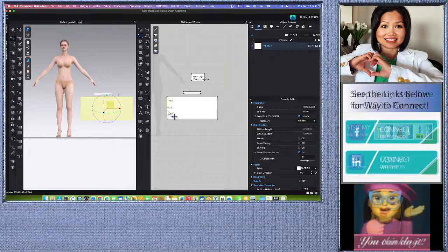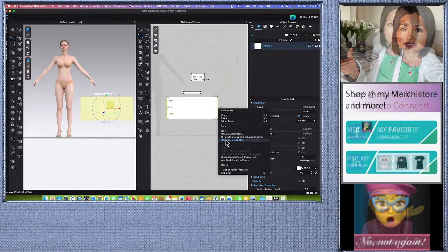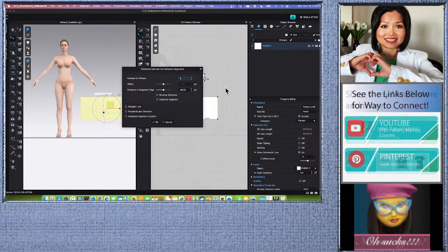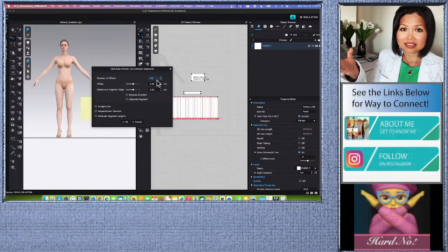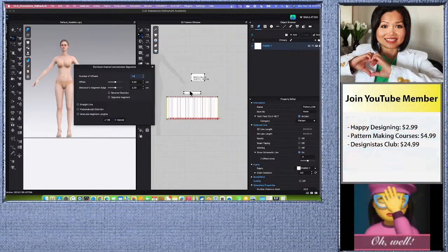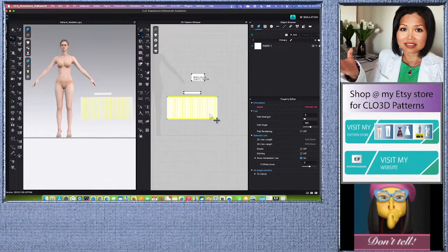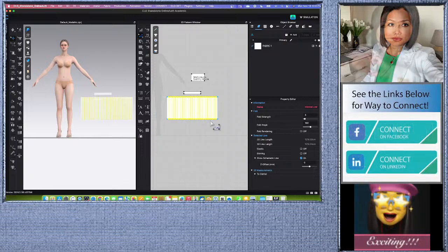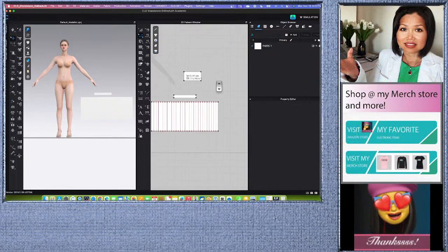We're going to select one end right here, press shift, select right here and right click. Then we want to select distribute internal line between segment here, and here I'm going to type in 29. Okay, so here we have 29 internal lines. I'm going to click OK, and by default all the internal lines are selected. Okay, so right here this is important. I'm going to click once on the page to deselect for now.